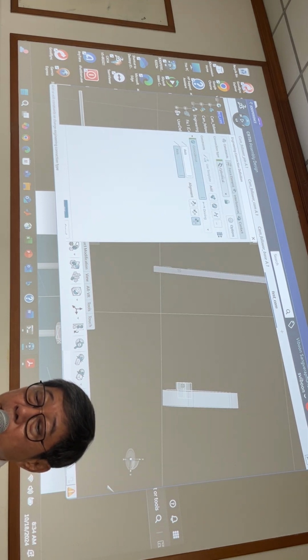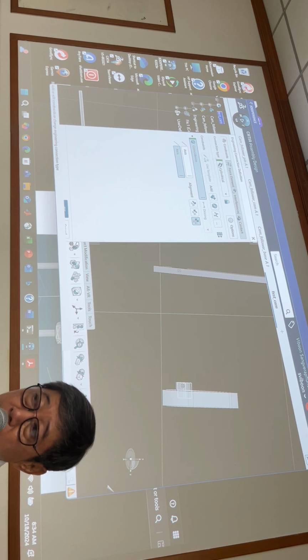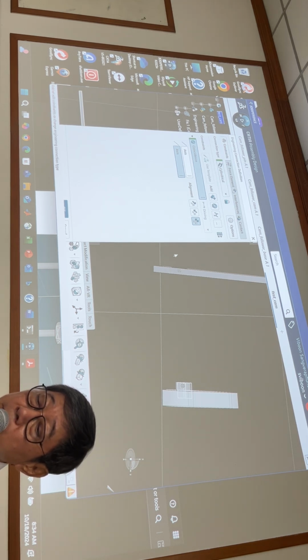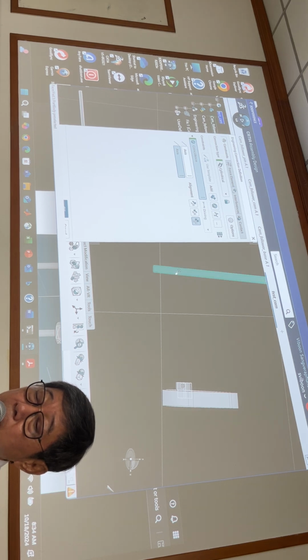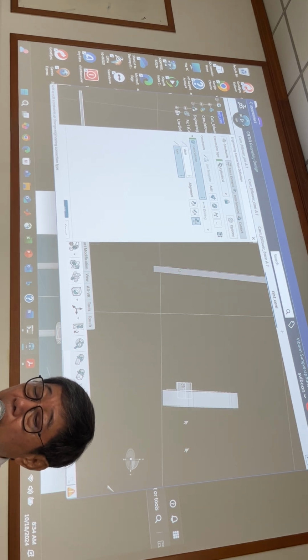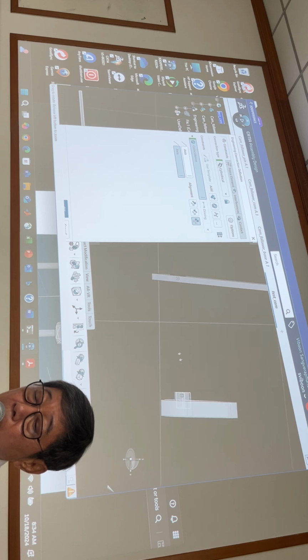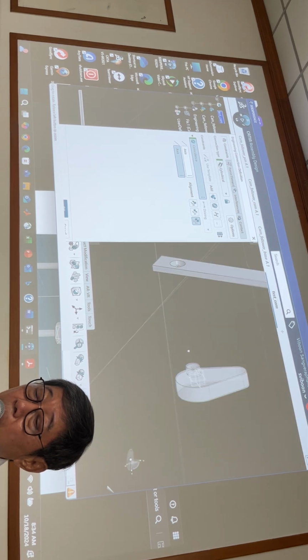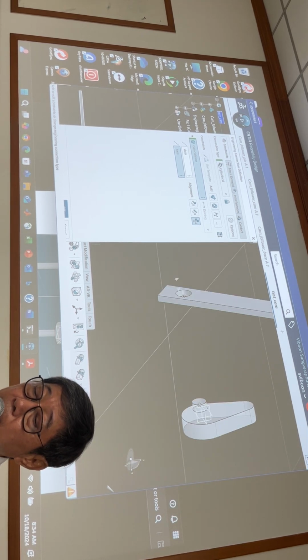Suddenly they change to cylinder, right? Cylindrical joint, you see. In that case, if you assign just only this, this joint is cylindrical. It means that it can be rotated as well as translate in this direction. Translate in this direction as well as rotate as well. In that case, but if I don't want them to be translated in this direction.